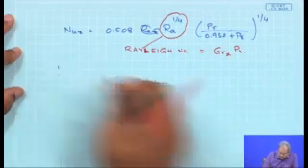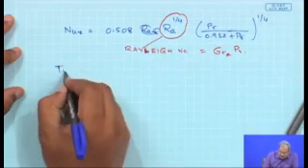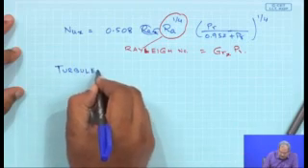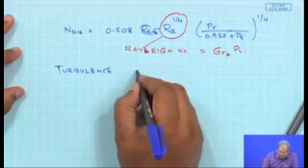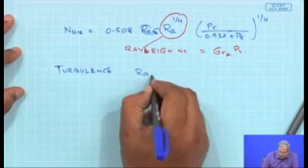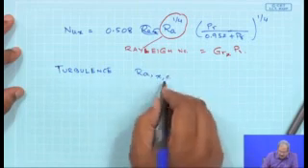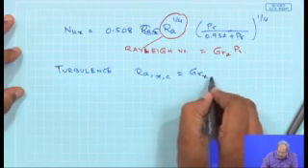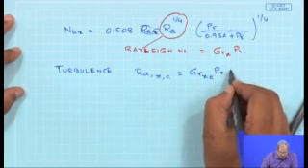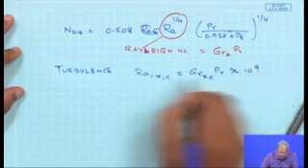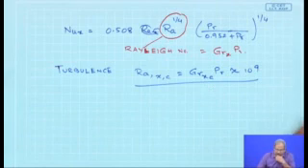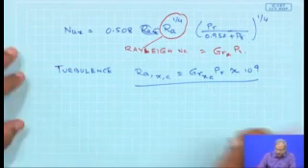So, under these situations, the turbulence in natural convection is defined when Rayleigh number at the transition, which is Grashof number at the transition times Prandtl number, is about 10 to the power 9. So, this is the limit for Rayleigh number for the case of turbulent flow.